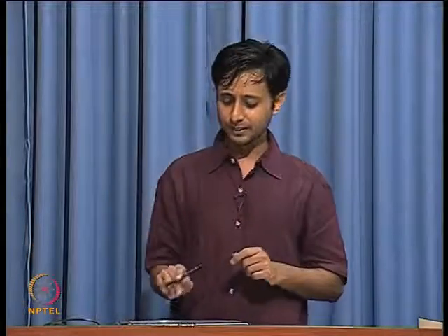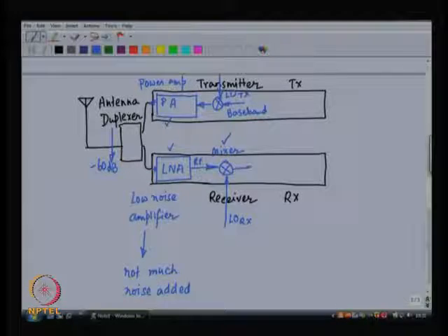So, in that case, the amount of receive power is so much, the amount of transmit power is so much plus 100 dB, the duplexer gives you 60 dB of isolation, which means that the transmit power that you have received is 40 dB more than the signal that you would otherwise want to receive. So, it basically kills what you want to hear, you do not want to hear this.